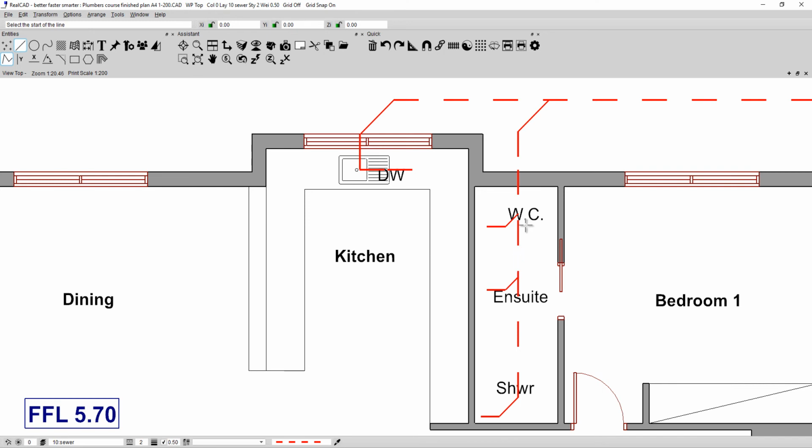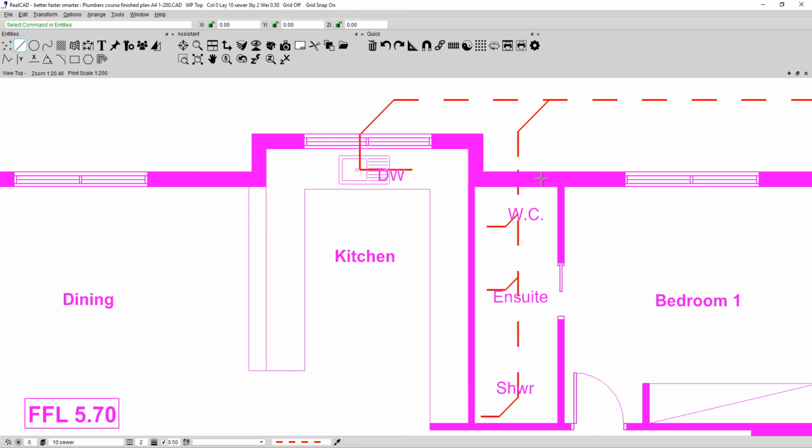Alright, so your drawing, if you've edited it correctly, may or may not have text in it. But if you do need to edit this, it has to be exploded first. We're not going to do it here, but if you had to, you would go to the tools hidden underneath the scissors, and there's a bomb, which is an explode command.